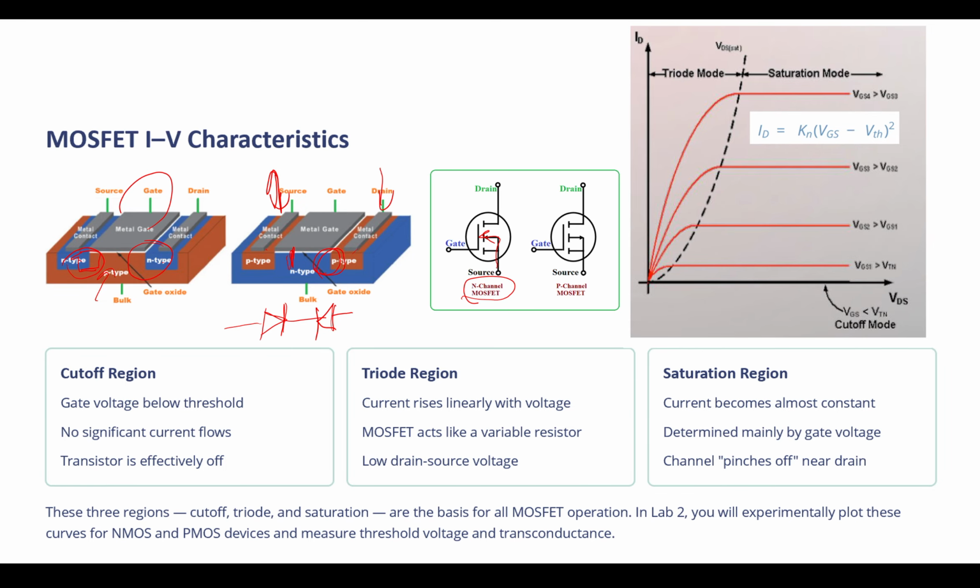So it doesn't matter what type of voltage you apply or what its value is, one of those diodes is always going to be reverse biased. That means no matter what happens, we don't have any current passing through the semiconductors. Is that clear?